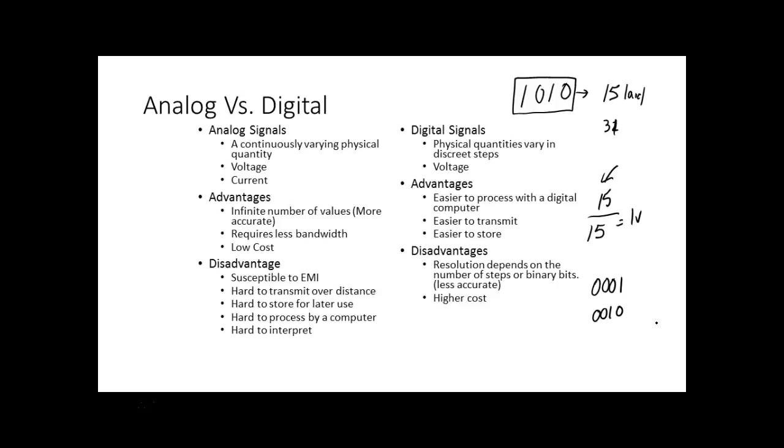A lot of the A to D converters that we have inside, so a lot of PLCs deal with an analog world. We've got to understand that predominantly our world is analog, and our computers are what? Digital. So we had to come up with a method of taking analog and converting it into a weighted binary number, and these devices are called analog to digital converters, ADCs. These guys have been around for a long time.